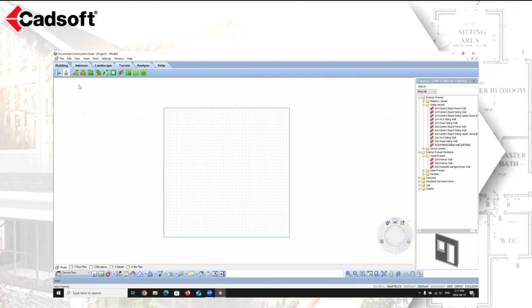So first, we're going to be taking a look at adding in hills and valleys. Now, to insert a hill or a valley, you can choose the Hills and Valleys button. Once you select that, it will bring up a command that will allow you to specify how high you want that hill to be. So you can adjust the value here by typing in a measurement that you want your hill to be in your design.